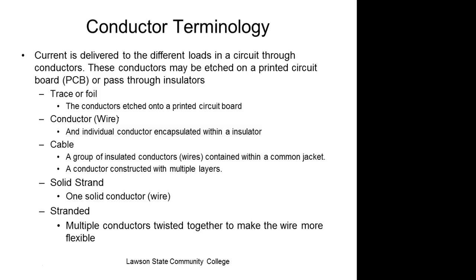So you have different cables with different jackets that are specified for different uses. I wouldn't go out and buy Romex and bury it underground, because that jacket is not rated for underground, right? So that's like when you see them on the side of the road and they're running that school orange.